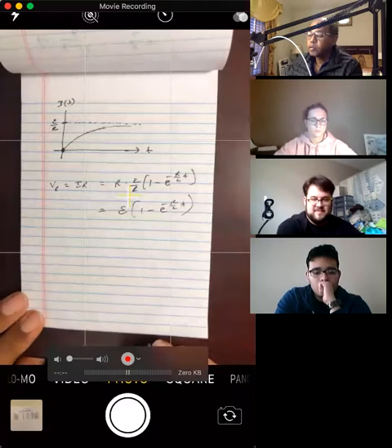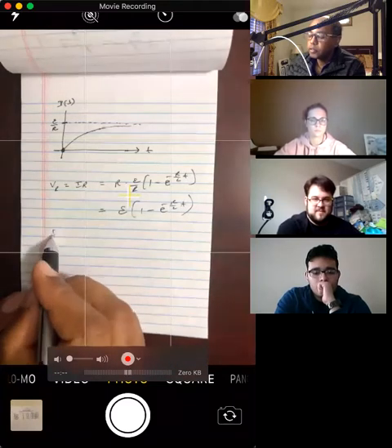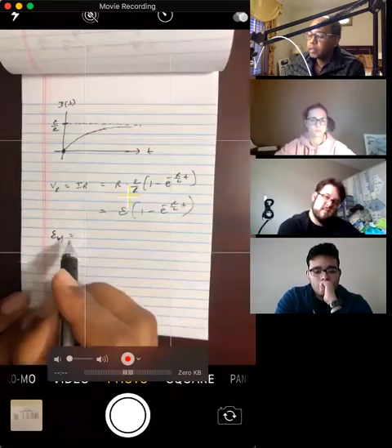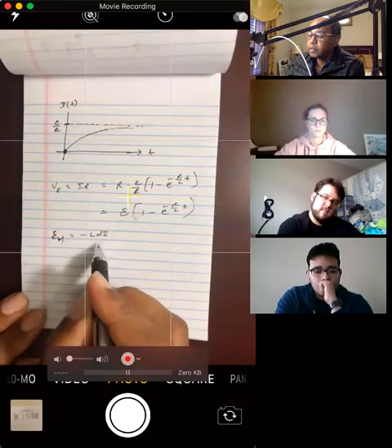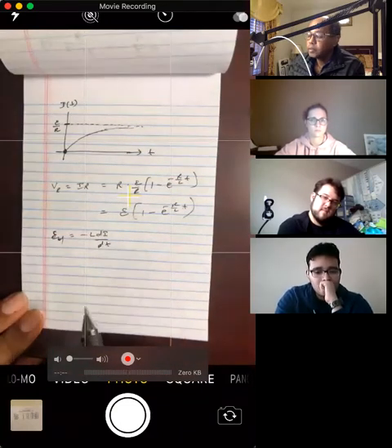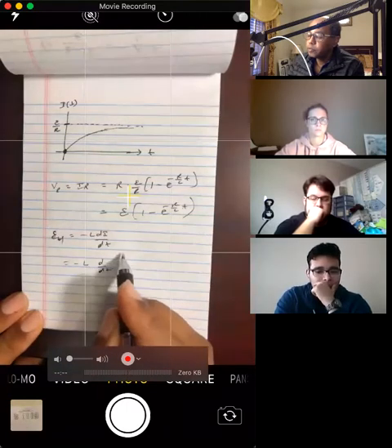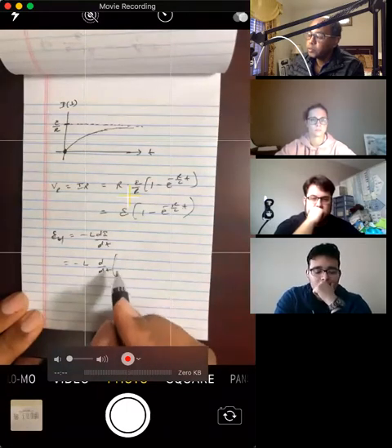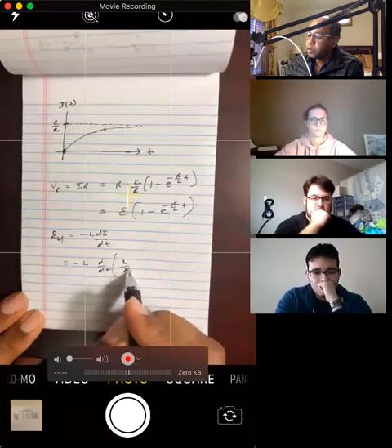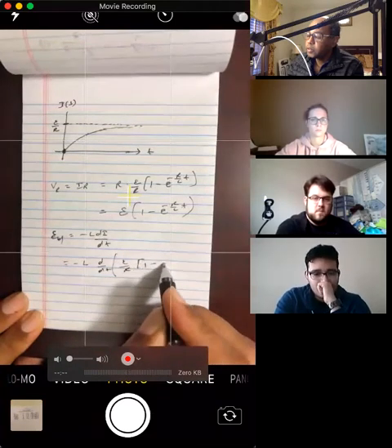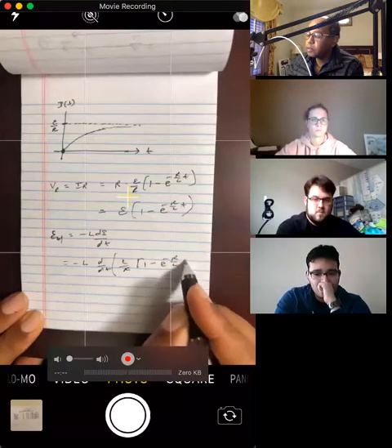If you're interested in the self-induced EMF, that's negative L di by dt, right? That's going to be negative L times the derivative of the current, which is E over R times 1 minus e to the negative R over L t.